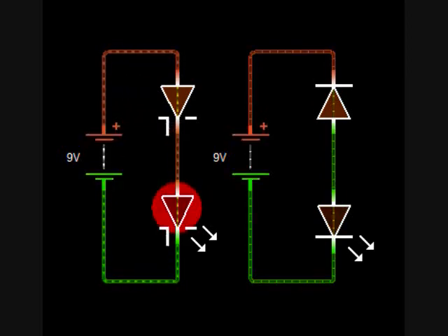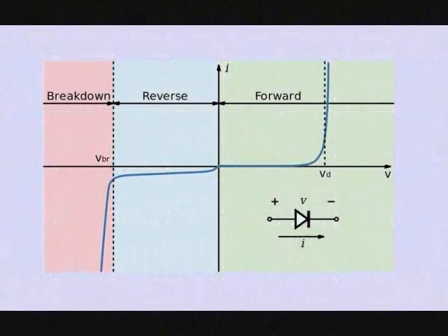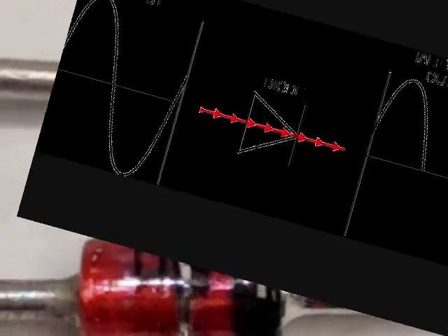The voltage current diagram means that in the case of forward bias, as the voltage increases, the amount of current through the diode increases almost linearly. It is like an open circuit. According to the structure of the semiconductors inside, each diode has the ability to withstand reverse bias up to a certain voltage, which is called the breakdown voltage, VBR.